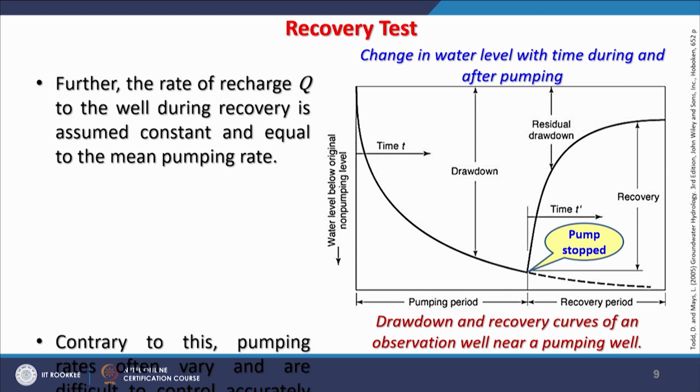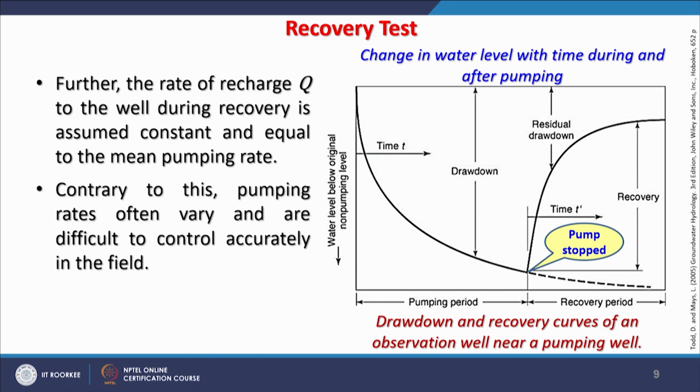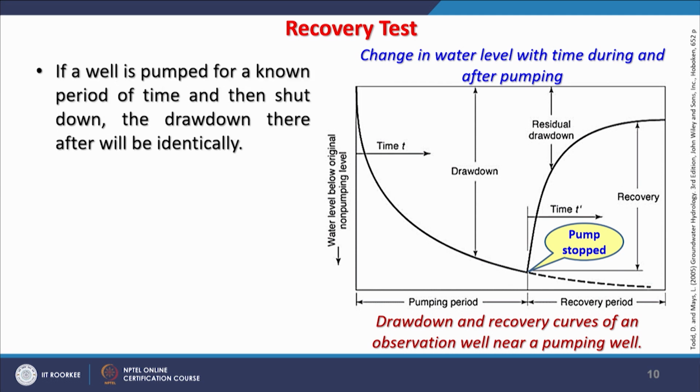This is the assumption we carry during the recovery test, whereas pumping rates often vary when we are withdrawing water. In the first part of this figure, where we are withdrawing the water, the pumping rates can vary and are sometimes difficult to control accurately in the field. So, for that purpose also it is good that recovery tests should be performed.